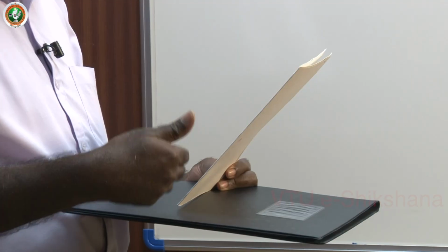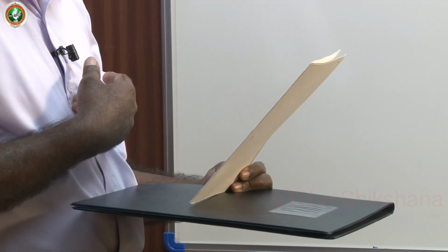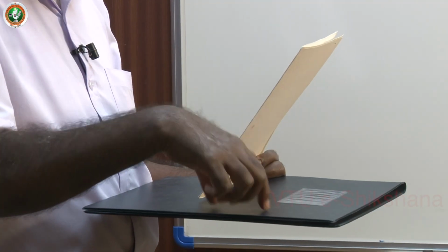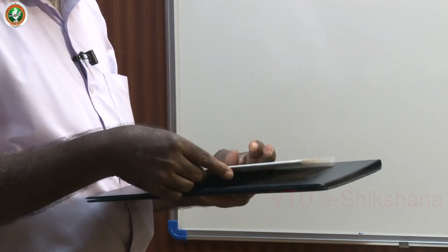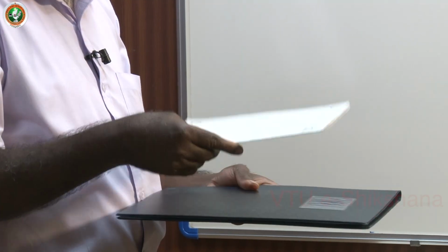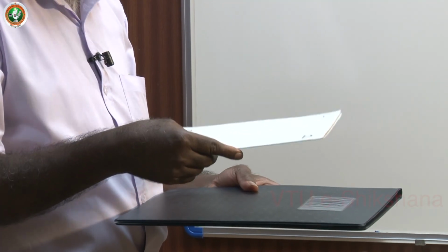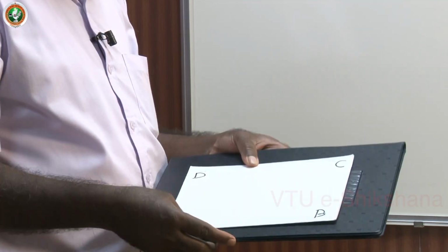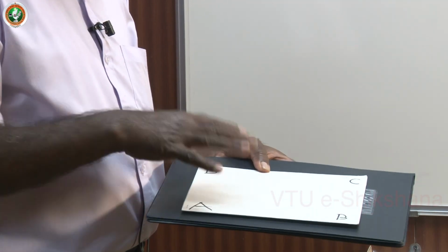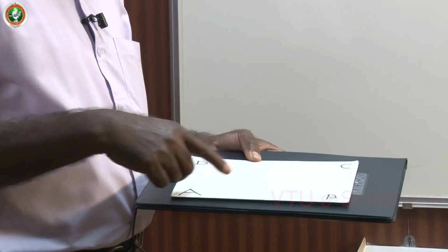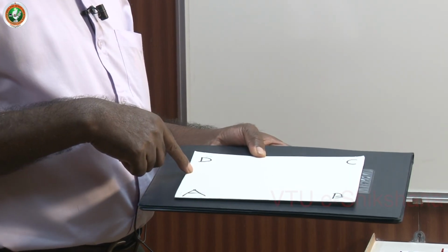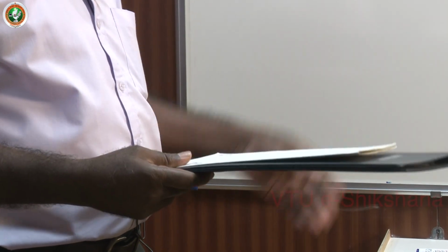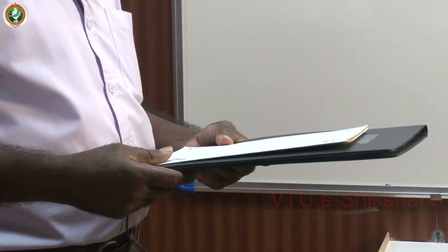If you project this, you will always get a line as the front view. And what is the top view? Top view is the apparent shape. Okay. If you keep it on HP or parallel to HP, you always get the true shape of the lamina. So if I keep it like that, what is the projection? The projection is this itself. Then you will get a rectangle 100 by 60 say, or 100 by 50. 100 by 50 is the top view. What is the front view? Front view is a line that is on the XY line, coinciding with the XY line.